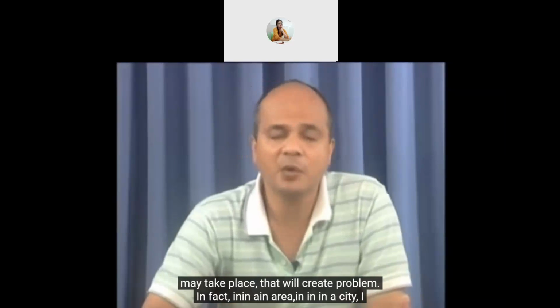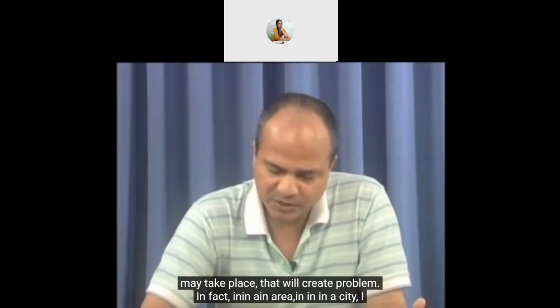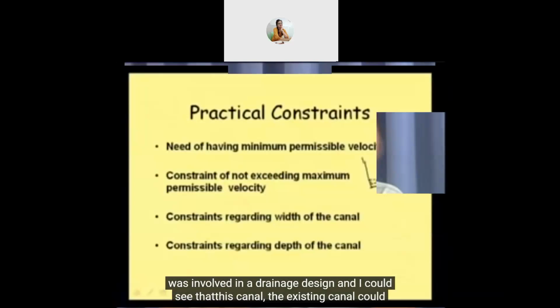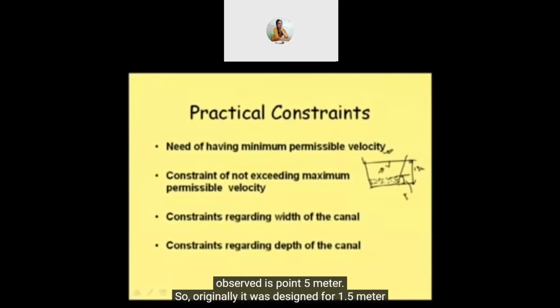That will create a problem. In fact, in a city, I was involved in a drainage design, and I could see that the existing canal could not serve because the total depth is 1.5 meter, but the depth of sediment that was observed is 0.5 meter.